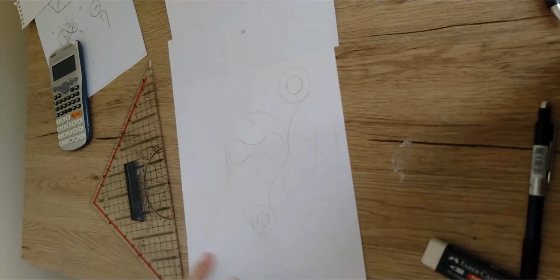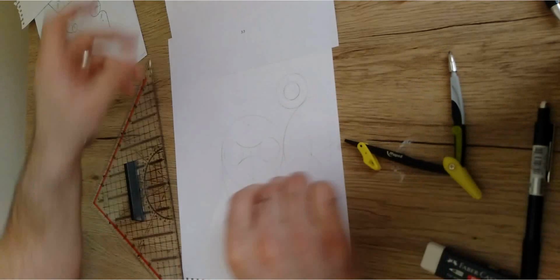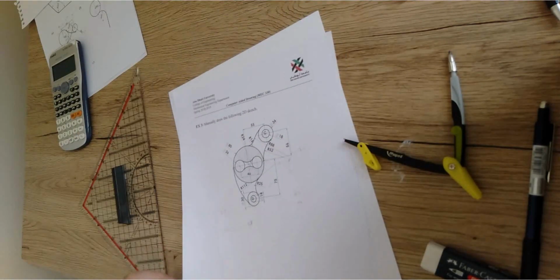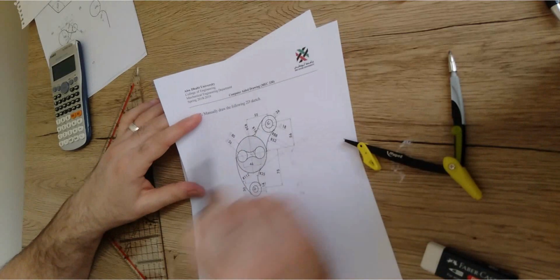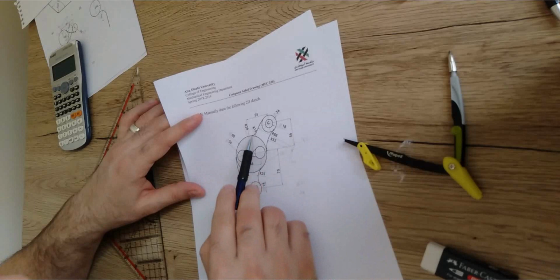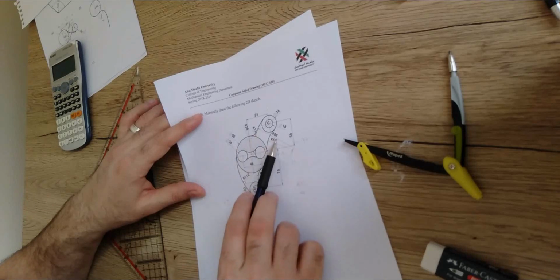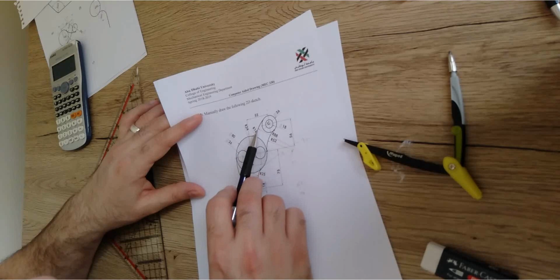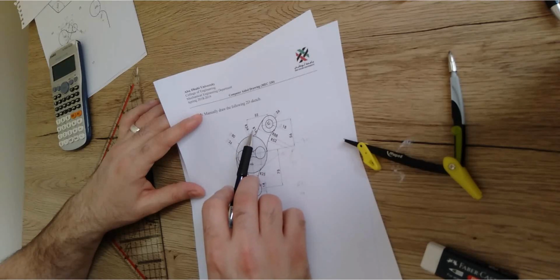Make sense? So I've finished all the curves except these two curves. These two curves are a little bit tricky because, as you can see, I do have two curves that are tangent to each other. So what does it mean? It means that there is a small curve here, which is this one, with a radius of 88. Then the 16 is tangent to this curve with a radius of 88, the curve with a radius of 16. You got it?